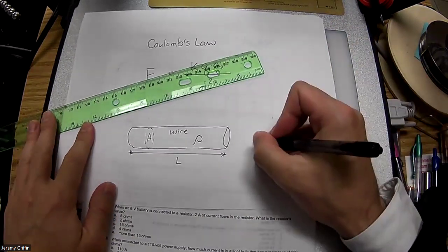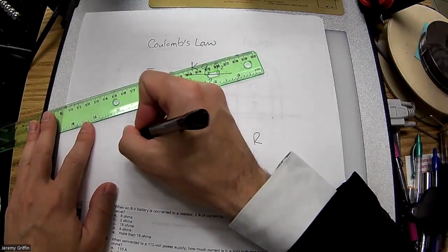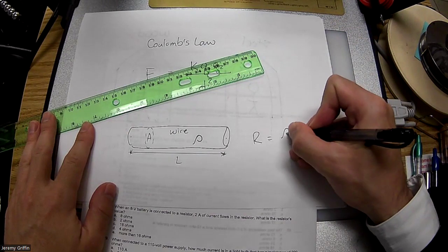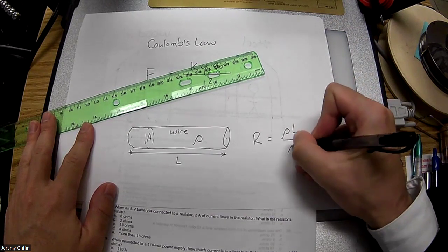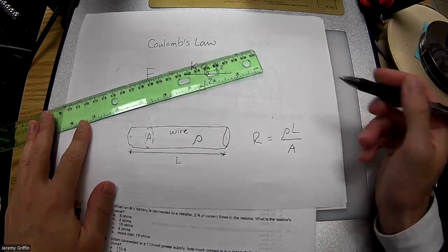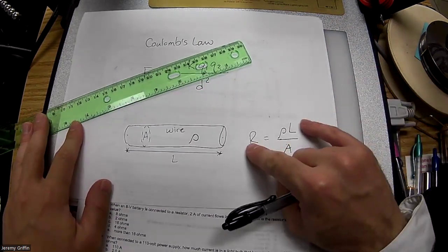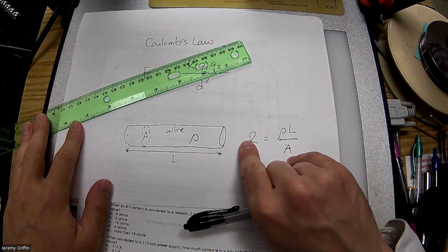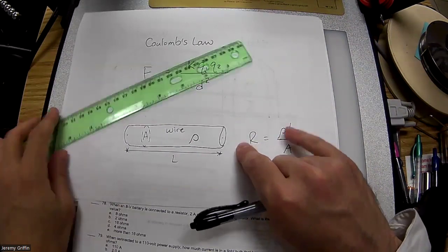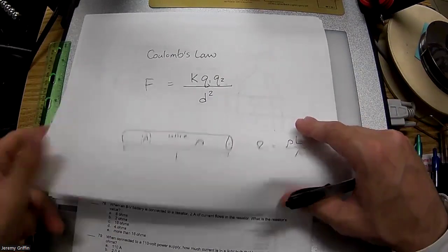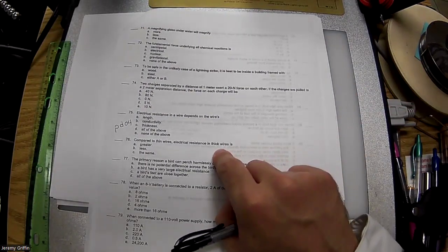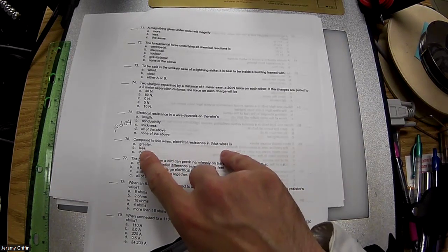And then the resistance from end to end, you guys remember, it's resistivity times the length divided by the cross-sectional area. The longer the length, the more the resistance end to end. The wider the wire, the less the resistance. Inverse relationship. And there's also some material property. Okay, so check that. Compared to thin wires, thick wires, I think thick wires is not as much resistance.